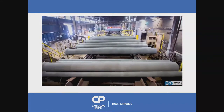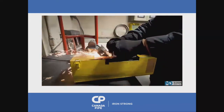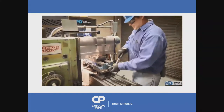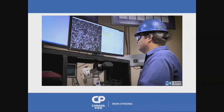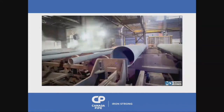This is the process right here where we're basically just beveling edges, which is done by hand. This is the testing facility. They will test a pipe every 15 minutes, and we'll test for the metallurgy of the metal. We'll test for impact strength and tensile strength. It's tested to a very specific AWWA standard.